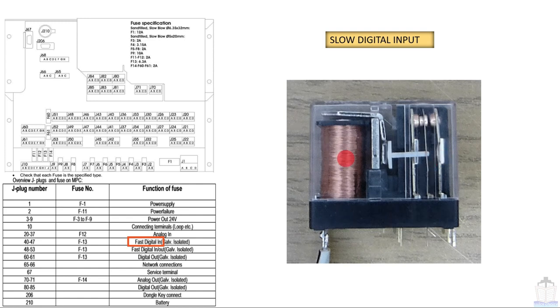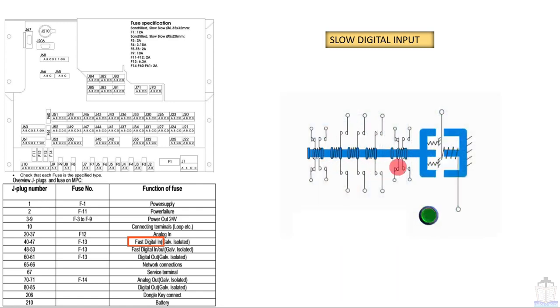So even though I switch on switch off power to this magnetic coil, I will not get 20 times make and break of these contacts because of some mechanical delays. So that is why these are called the slow digital input. That means all mechanical equipments which generate digital signal, means making breaking the contacts, will be termed as a slow digital input. Similarly, same thing, this is the contacts of the magnetic contactor. This has also the same problem, means some inertia is there. So we cannot make it as fast as the fast digital inputs are there.